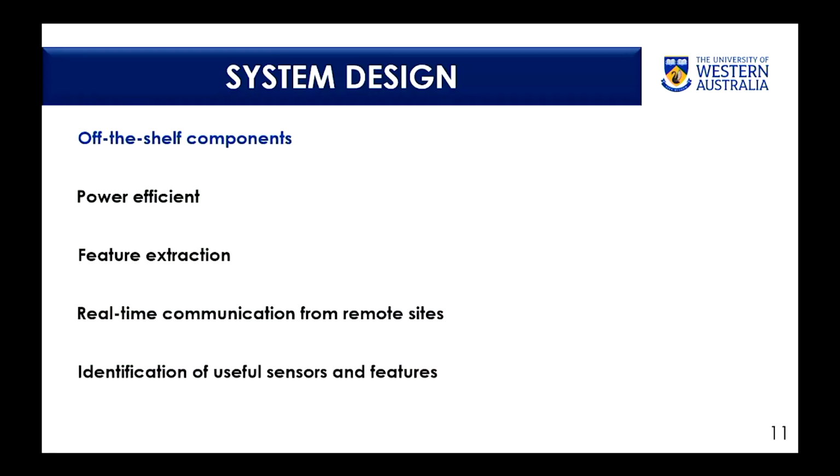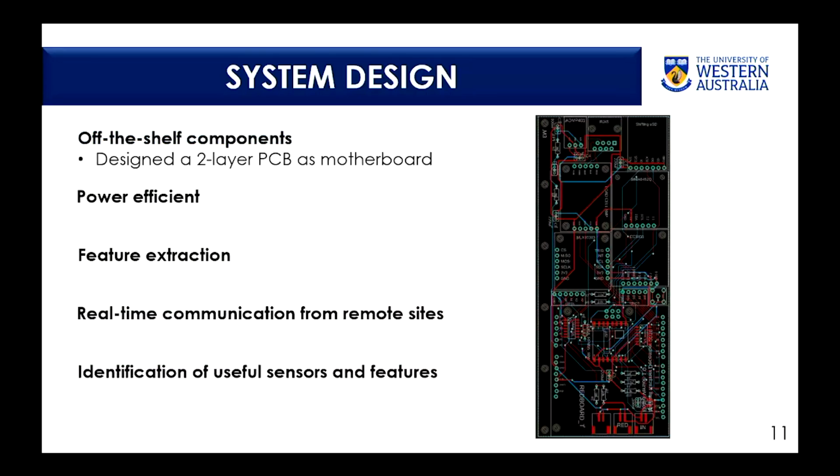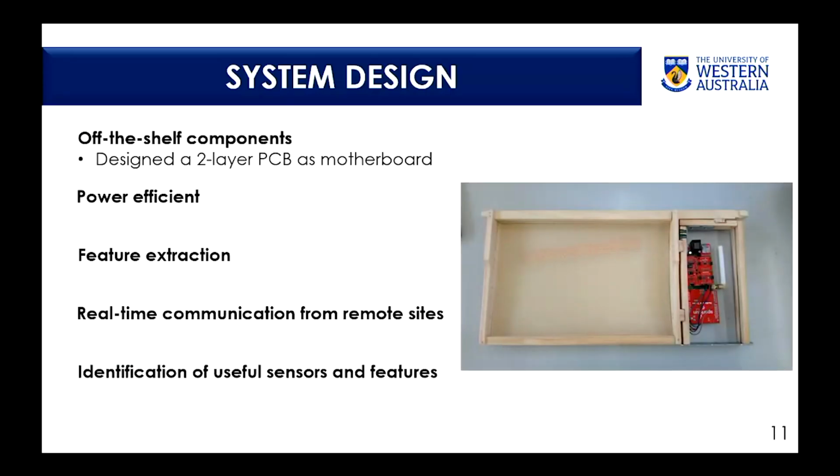We designed the system using off-the-shelf components that were very easily available. We designed our own PCB, which is a 2-layer motherboard. It can house different sensors in different locations. This was the very first system that we made. It took a lot of space on the side of the frame and didn't look nice, but again, it was just to get a feel of whether the systems and sensors will work or not.